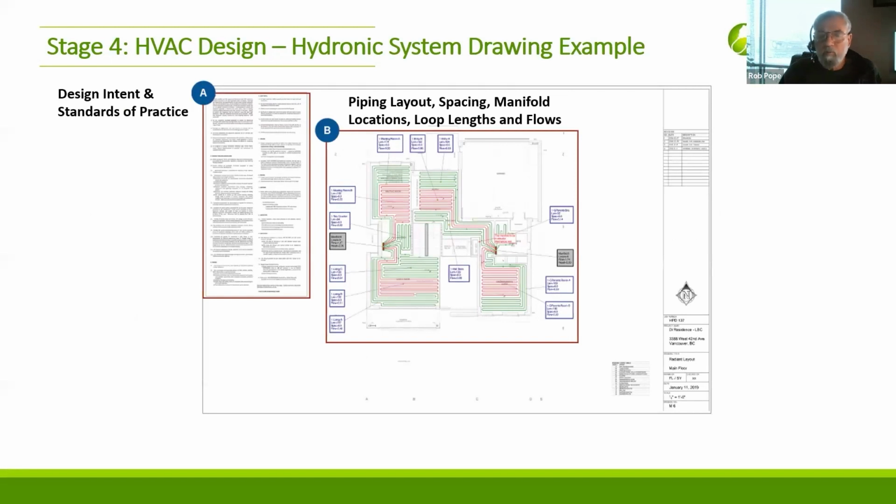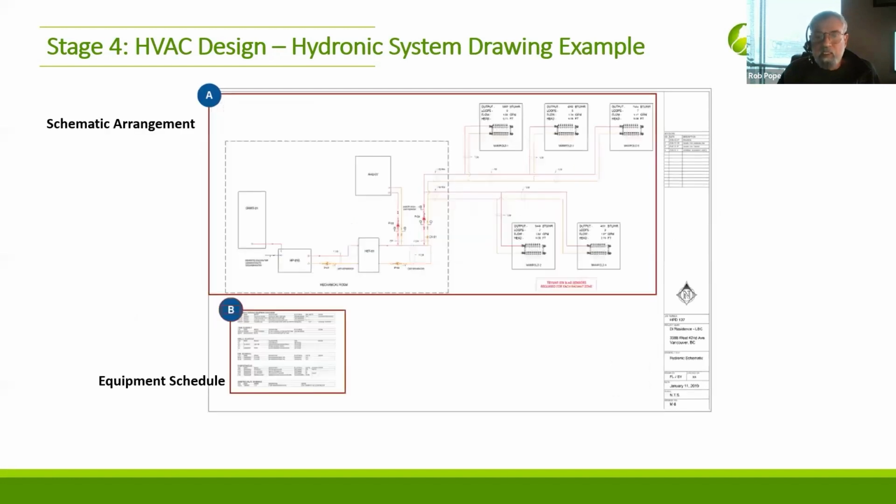Primarily loop layouts in the floor that's going to be covered by lightweight concrete of some sort of topping, manifolds, that kind of stuff, GPM, pressure drops, all that. So there's a standard approach for what that kind of design looks like. And it'll have a schematic, this is the hydraulic schematic, how all that water is moving, all that liquid is moving.